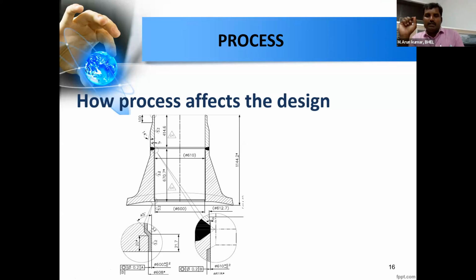So we were trying to weld this cladding with austenitic stainless steel material. What happens whenever there is a minor repair on this austenitic stainless steel? We used to make grinding and build up, or if we get a small PT indication, to remove those PT indications, we used to do grinding of that particular region.